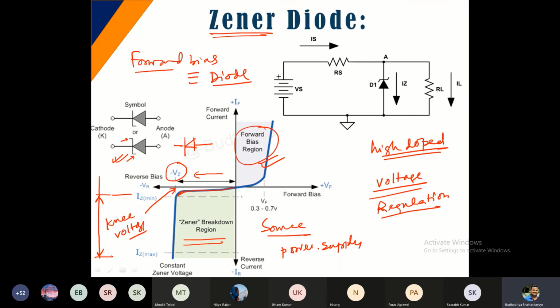Now suppose there is an anomaly at the source, where a huge current is coming in and you want to restrict it. With a Zener diode, after the knee voltage is reached, even if the current is more, there will be hardly any change in the voltage. It stays constant, so it avoids any damage to the device due to excessive heating or any other cause.